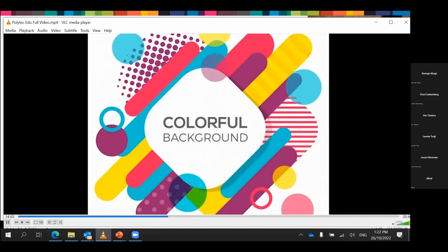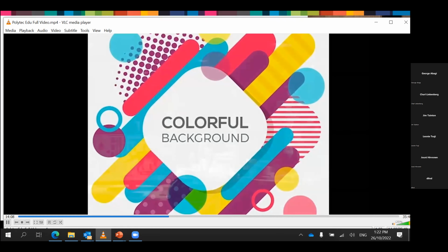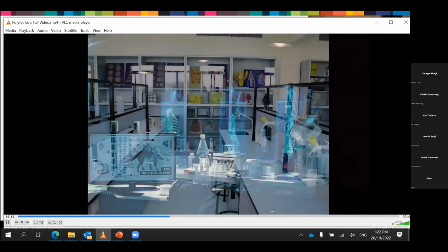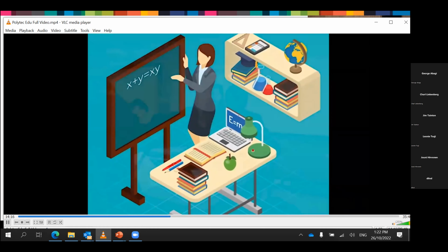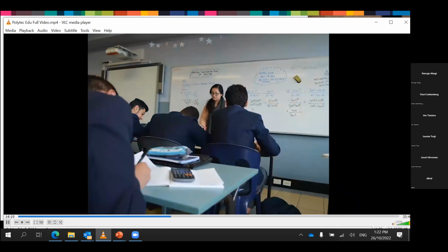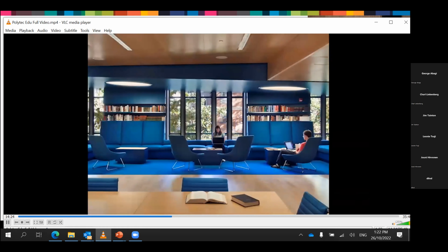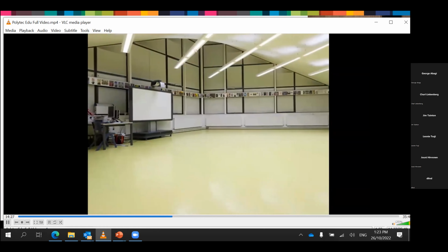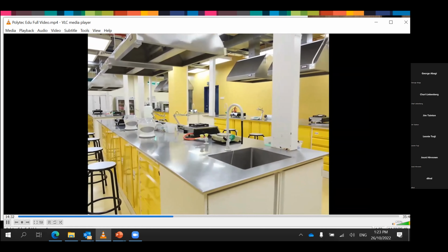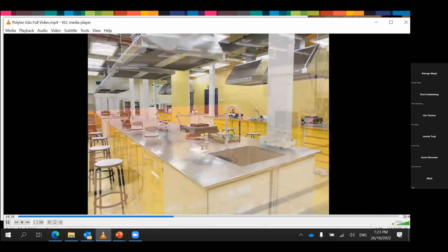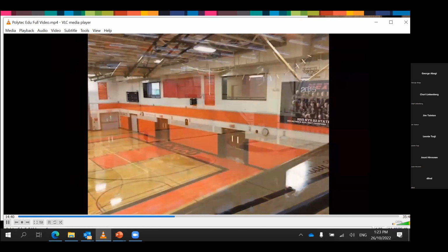The best colour selection for different spaces within the education building, which are best suited for specific environments, are: the blue colour family works well in science and math-based classrooms by lowering the heart rate and allowing concentration to kick in. For libraries, counselling rooms, and social studies rooms, the natural colours of balance, green and blue, are best. Gentle energy yellows are great for classrooms dealing with language and other creative pursuits like fine art, dance, and culinary arts. Oranges and peach tones support athletic facilities, drama, and visual arts.